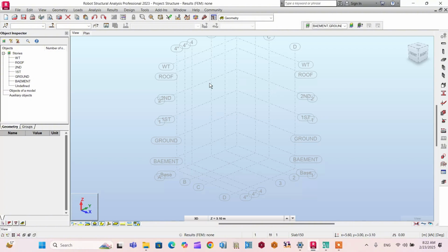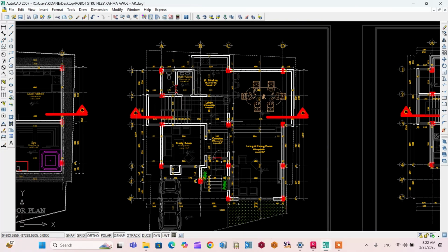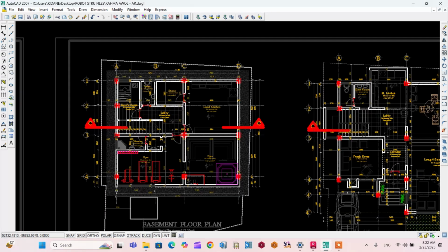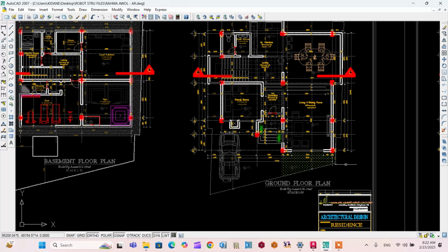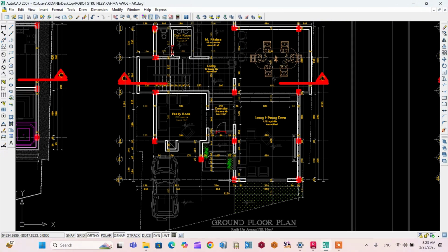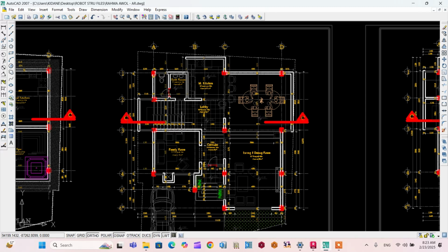So using these grid lines, starting from the basement floor, I will draw all the column and beam arrangements. So from the basement floor, all the column arrangement looks like this. I have 3 other columns that start from the ground floor, but not the basement floors. So using this data, I have to draw all column and beam layouts. After this file in the description box, you can get it. So let's start to draw our beam and column arrangements.